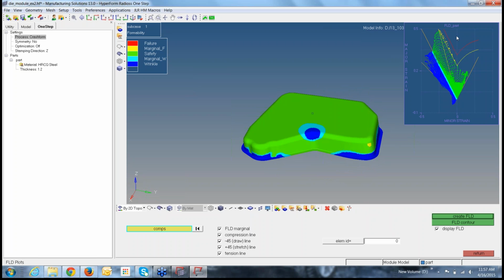This is called the forming limit diagram or forming limit curve. First, based upon your blank thickness and your strain hardening coefficient, this point is calculated. Then these two curves are plotted 45 degrees to each other. It's offset down by 10 or 15% based upon your marginal value, whatever you have specified. Then way down below, on your minus strain, you would see your good line or your proper forming line. Anything below that will be compression, above that will be forming good.